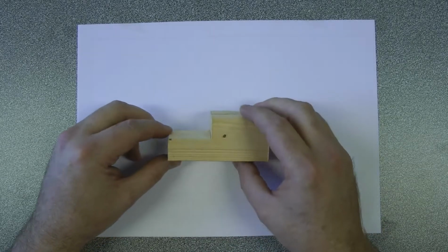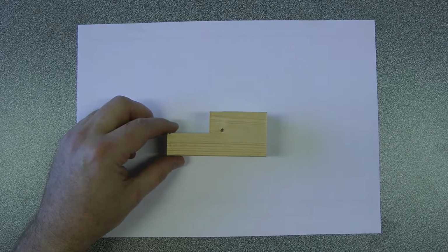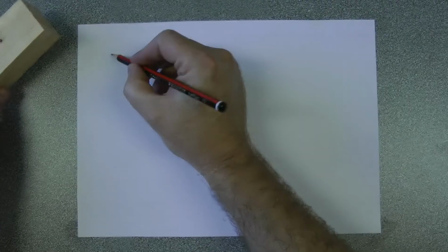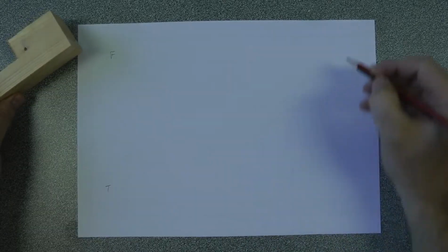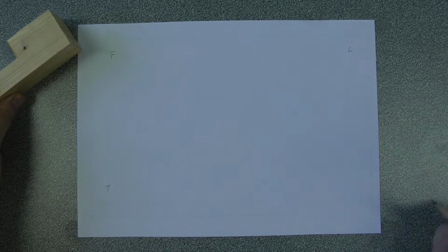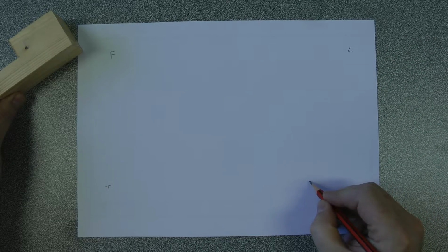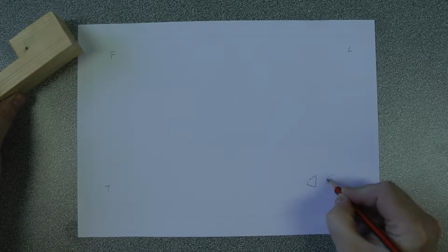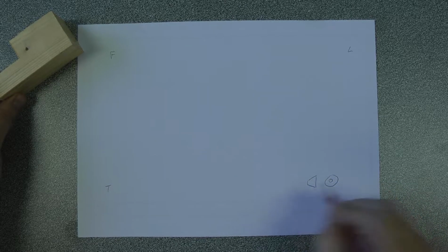So we're going to be doing that, and we're going to be doing it in first angle, which means that we're going to lay it out, that we're going to put the front on the top left of the page, the top is going to go below it, the left side is going to go to the right. Okay? And we show that, if you ever see it on a drawing, it looks like this, which is a cut-off cone that's rotated onto its side.